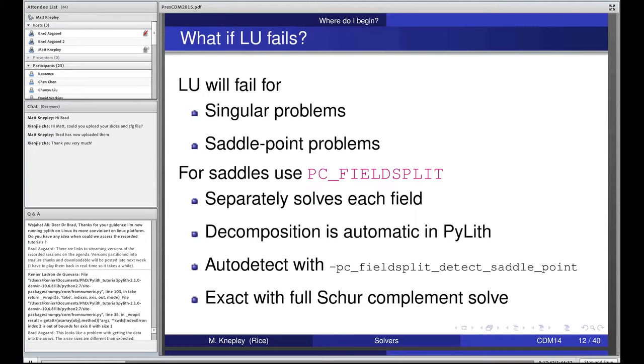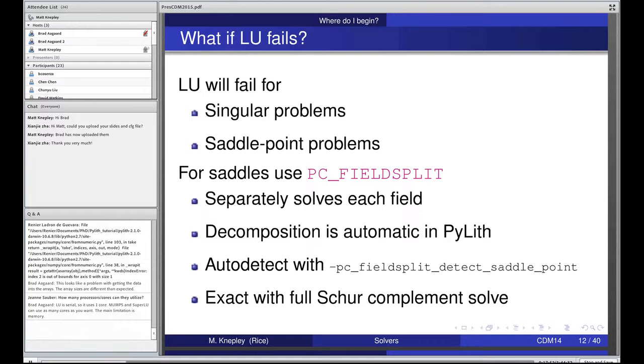Here it's a constraint on the separation between a node on one side of the fault and a node on the other side of the fault. So for instance, if you had a kinematic fault description, those would be fixed. If you have a frictional fault description, the constraint will be that the force necessary to get that separation agrees with the Lagrange multiplier, right?